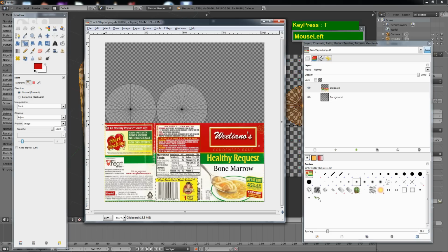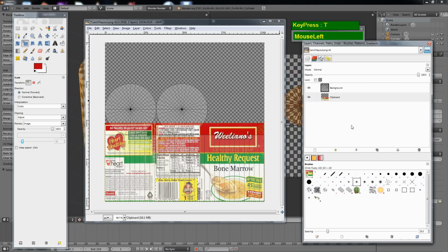As you can see, I slightly overlap this, but I can change the scale later on. Now you notice that this label is falling above the layout. So what I want is for the label to be below the layout. So you can go to the layer sequence. You can click on the arrow here, select the top layer here, and click on the arrow to bring it below the layout. So you can see the layout lines cutting over the texture. So you can use this as a guide. So I need to scale this label down a little bit more.